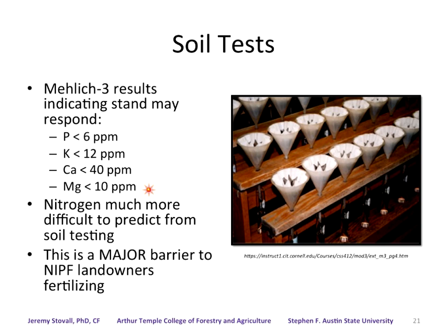And so typically when you do soil tests, all these soil testing labs are really set up a lot more for agriculture, where you're dealing with an annual crop that's generally shallow rooted, and so all the sampling tends to occur in the top 6 inches, 4 inches of the soil.